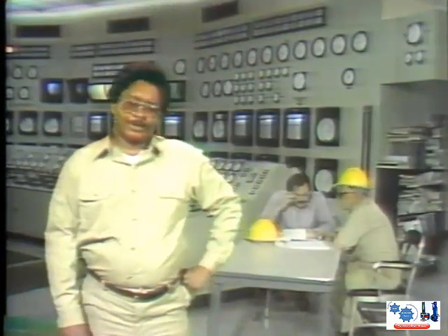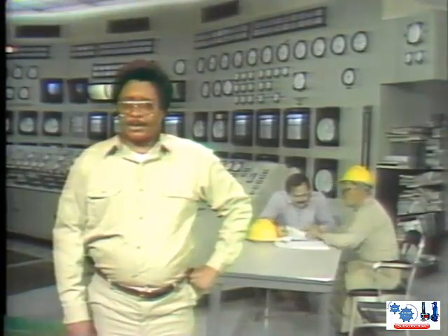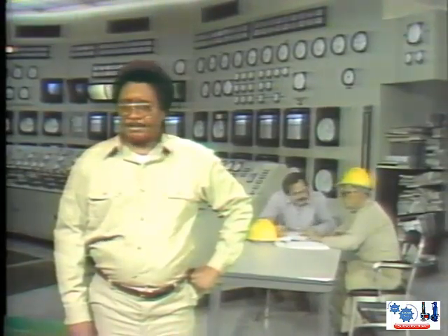So far in this unit, we've concentrated on tables 1 and 2 of the steam tables, those that deal with saturated water and steam. You've also learned that close estimates of the properties of subcooled water can be found in these tables as well. The third table that we need to cover is Table 3, superheated steam. Table 3 gives you information about the properties of superheated steam, but it's organized differently than the tables we've looked at so far. We'll use atmospheric pressure as our example again.